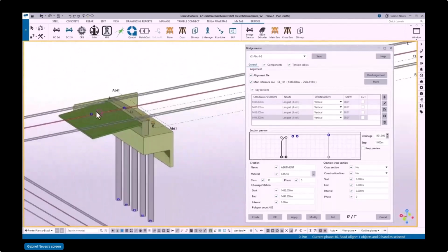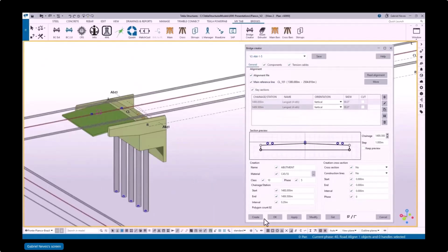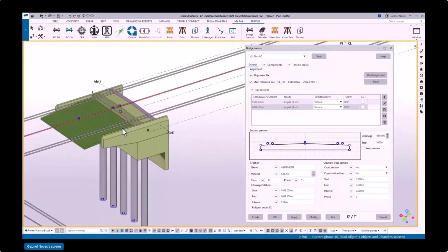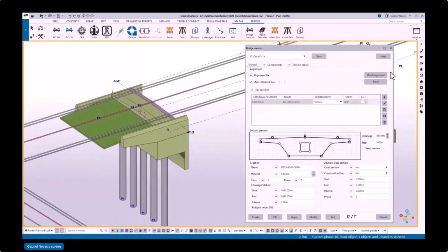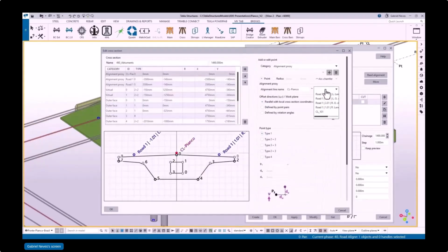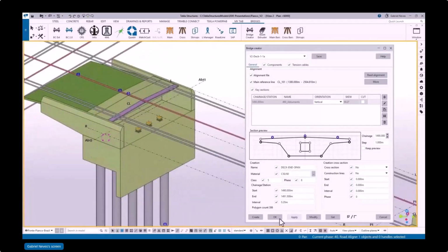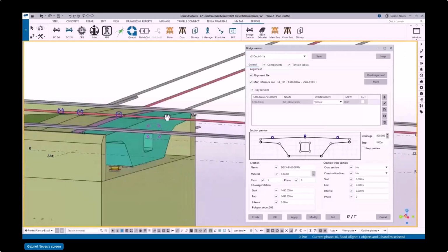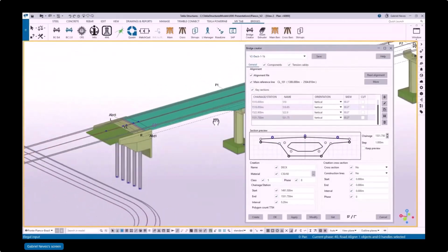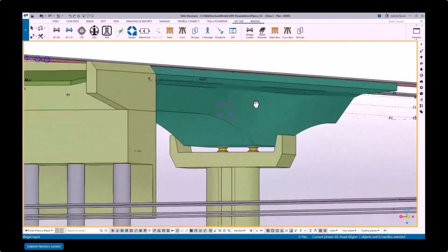So Bridge Creator is connected with the road, extruding the objects, and some of the objects, the top follows the road, the bottom is flat, because if we put a virtual point with a Z, then we can constrain the soffit of the objects to that virtual point. That means the object is horizontal in the bottom. Just to remind you if you don't know about that. So here just the opening. All these cross sections can be as complex as you want, including the longitudinal parabolical variation, and just loading files here. So the bridge is done just for some time, just placing that.